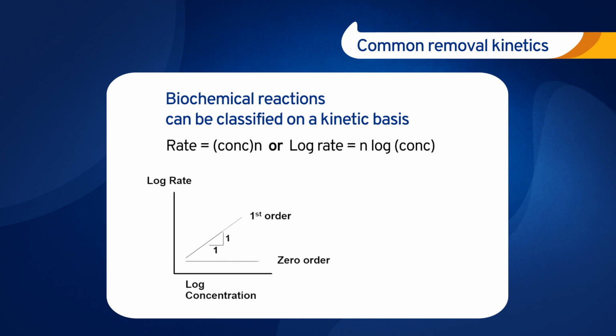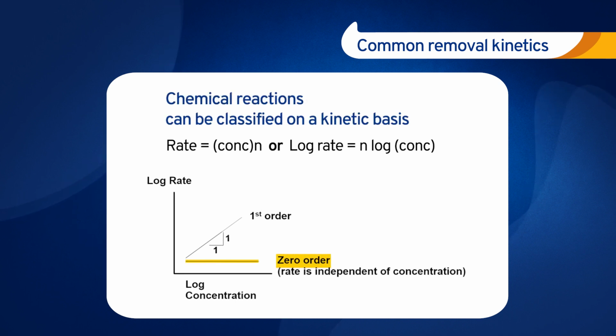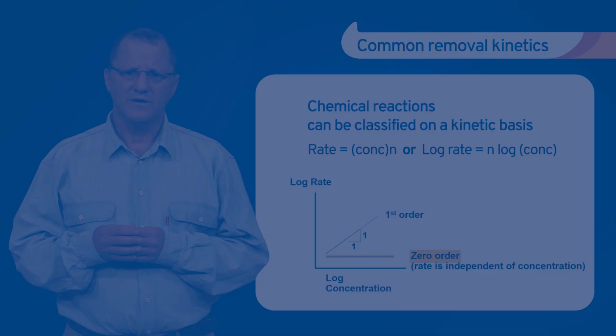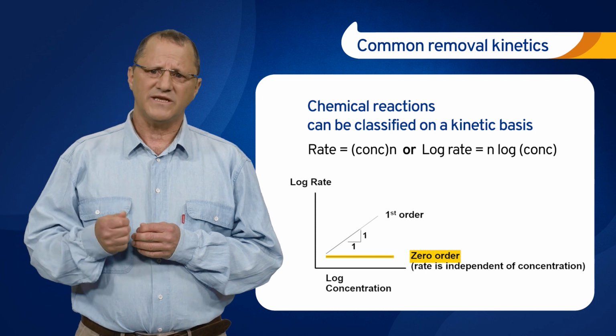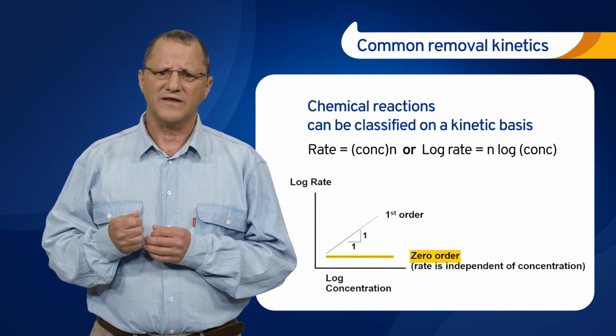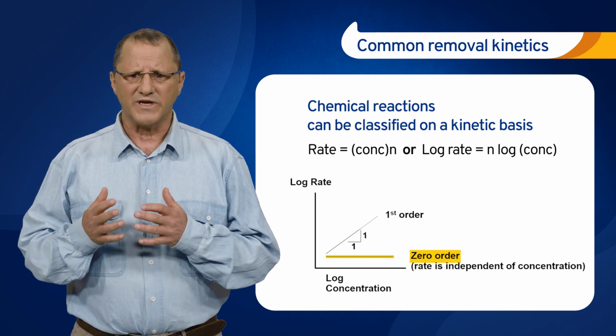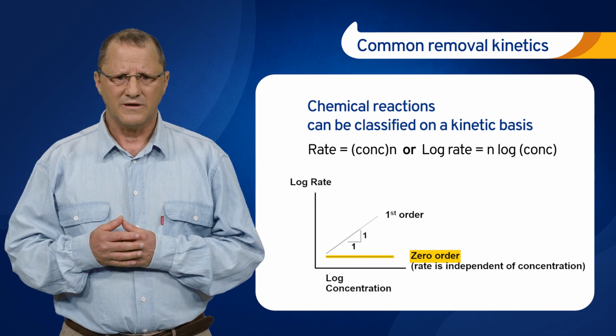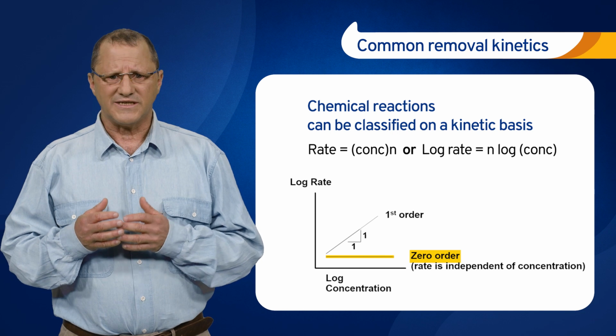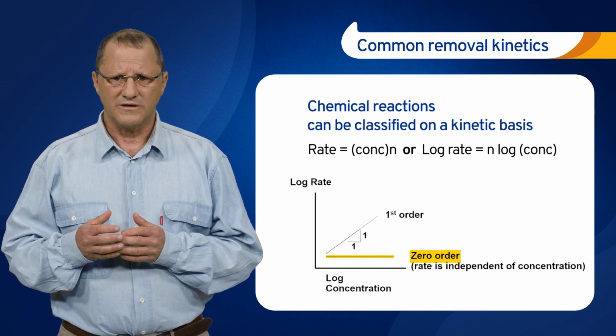Interestingly, typical biological degradation rate was empirically found to be logarithmic and can also be described by either zero or first-order kinetics. Zero-order kinetics refers to a constant biodegradation rate that is independent of substrate concentration. So in our example, it means that the reduction of organic matter over time will be constant regardless of its concentration. Zero-order kinetics is typical for higher concentrations.